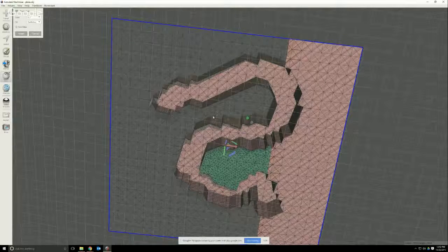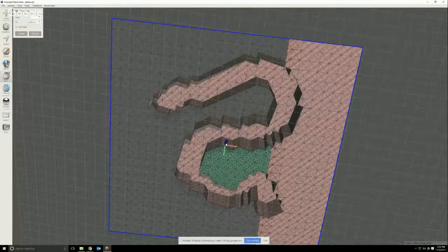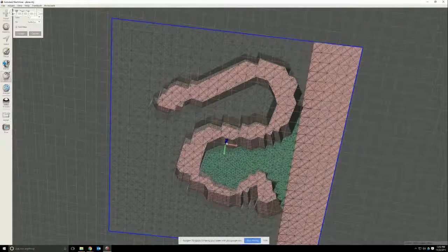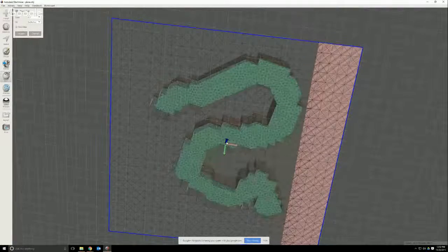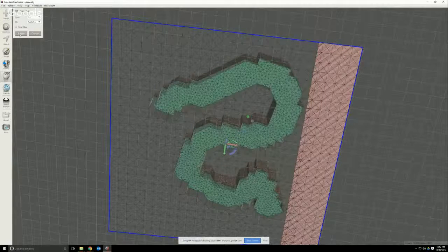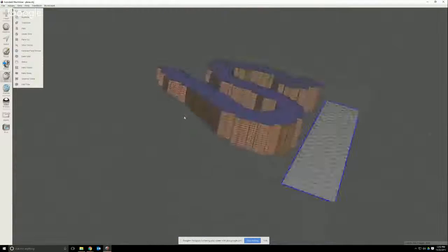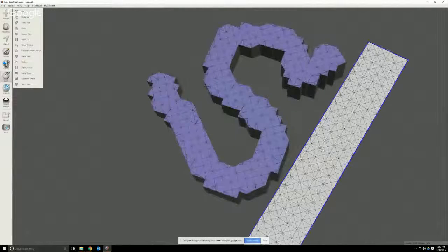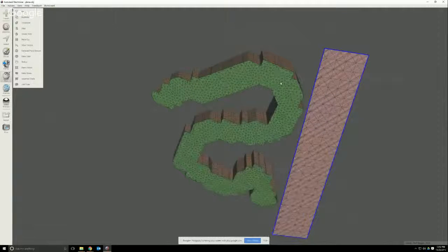So the plane cut command isn't going to work as you think it would. You would have to move this up and up until finally, boom, you get an outline there. I cut it, but I didn't cut it enough to get rid of this. So that preview really does show you when you're cutting appropriately for the Plane Cut tool.